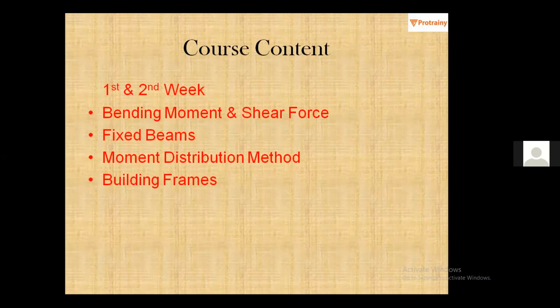Another thing is that, in my experience, the slope deflection method is a very good method and comparatively easy. But for a continuous beam, if we are moving onto a portal frame or something complicated, that method starts becoming tedious. Well, with the moment distribution method, the degree of tediousness stays the same, whether you are doing a single beam, a continuous beam, or a portal frame, single story portal frame, double story portal frame, single bay portal frame, or double bay portal frame. It's like that.